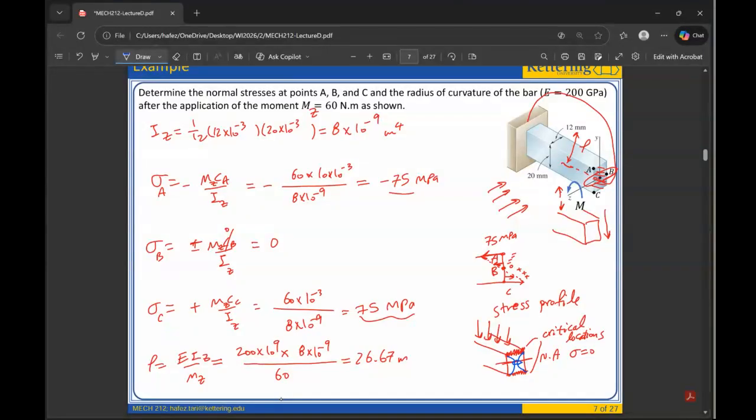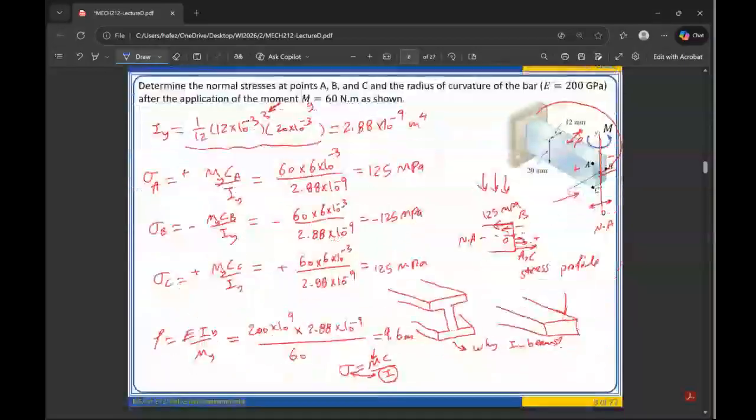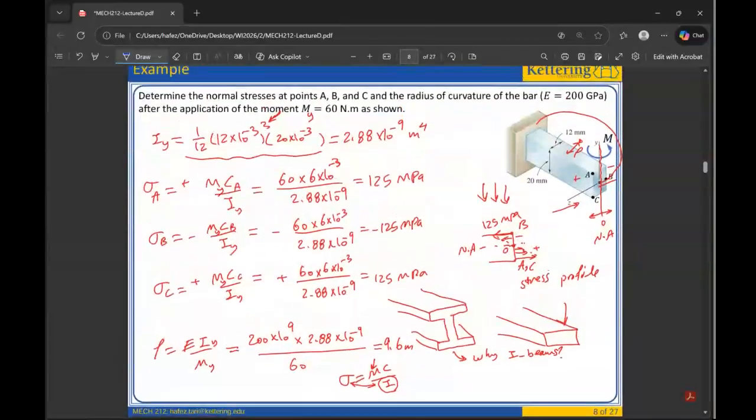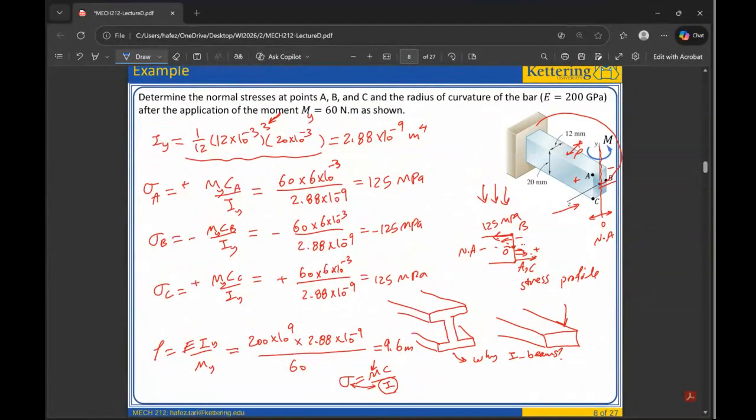So take out the majority of material from the middle and instead strengthen these two locations as needed, but not much is really going through the intermediate interior segments. So for this reason, people said, why not make it I shape? Take out the material. We are making it lightweight, but this is important, with almost the same strength.